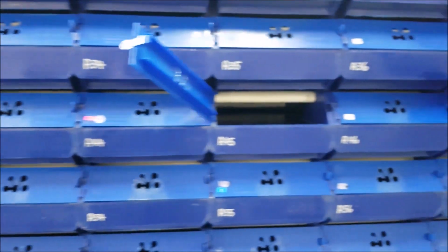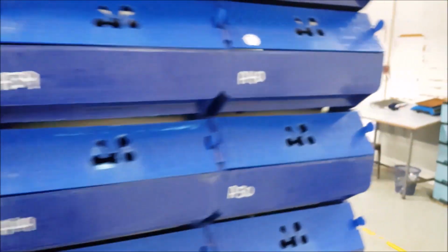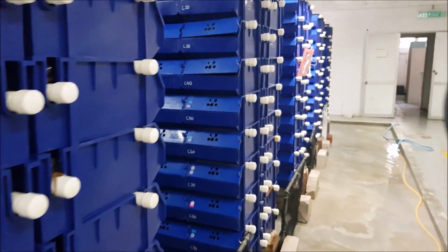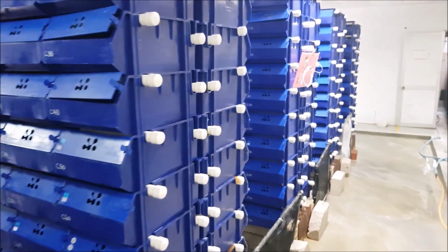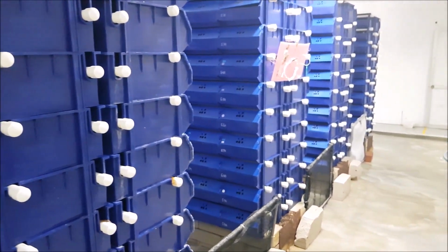In this case, what you see here, there is no water even going to the box despite the valve being on. This sometimes happens if your inlet tubes are too plugged, and that will result in water not being able to go into the box.